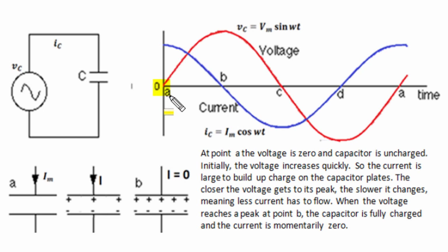Initially at time position A, the capacitor won't have any charge, but the circuit gets maximum charging current, and due to that charging current, plates will have an increase of charge and voltage across, and in the process charge and voltage across the capacitor go on increasing. For a higher amount of charging current, the rate of change of voltage with respect to time is higher, and as charging current becomes 0, the rate of change of voltage becomes 0 and increase of voltage ceases, and voltage attains its peak magnitude at time instant B. And in this first quarter cycle, the capacitor from 0 charge condition gets fully charged.